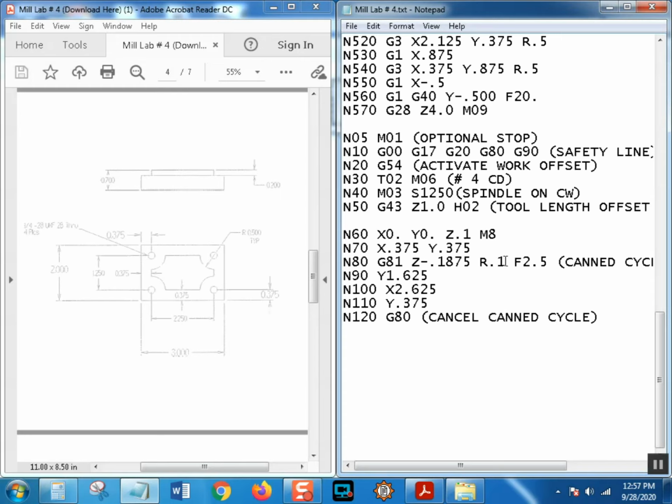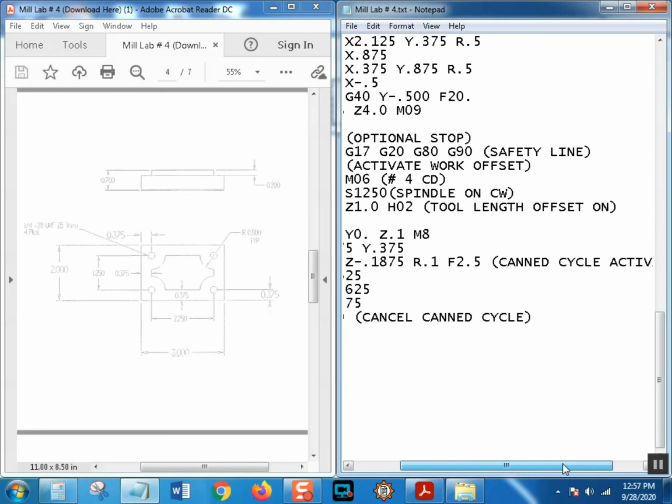So, besides that, if there's something bad going to happen, it might give your operator enough time to hit the e-stop button. But seriously, on the new controls that are running at 1,000 inches per minute at rapid, there is no way you can hit the e-stop button fast enough. You're going to break a center drill, you're going to knock things out of the line, God knows what other terrible things will happen. So, don't change that R.